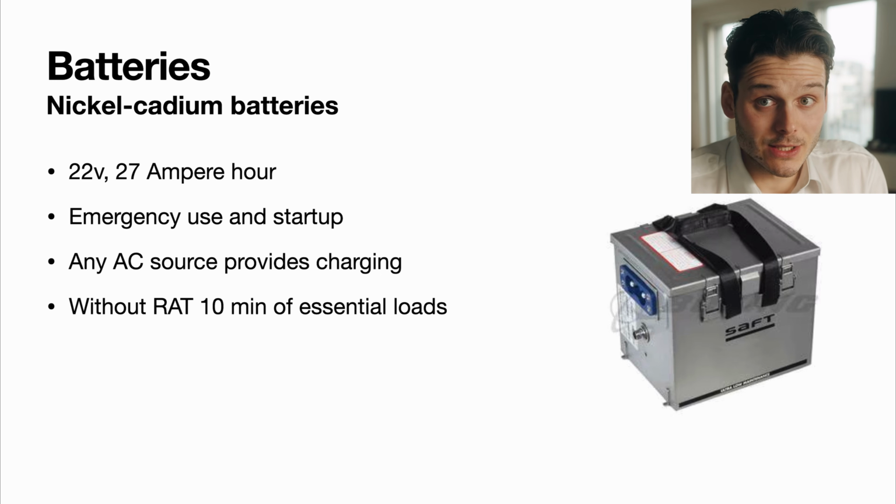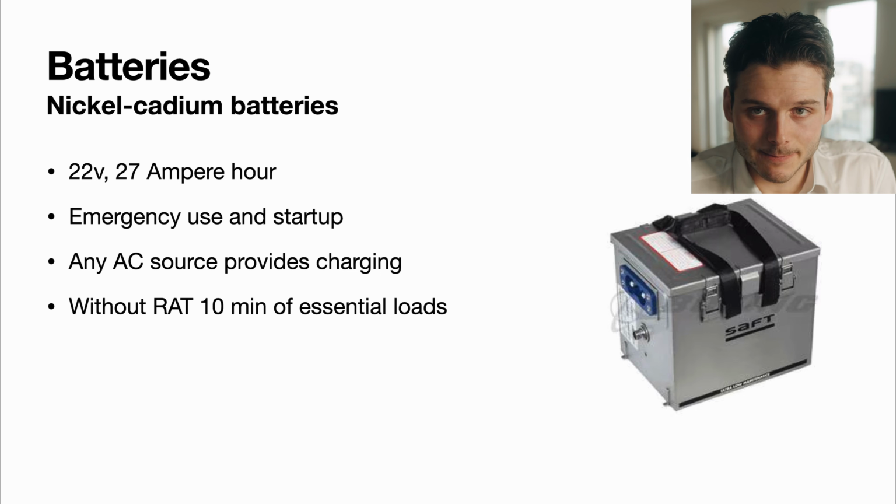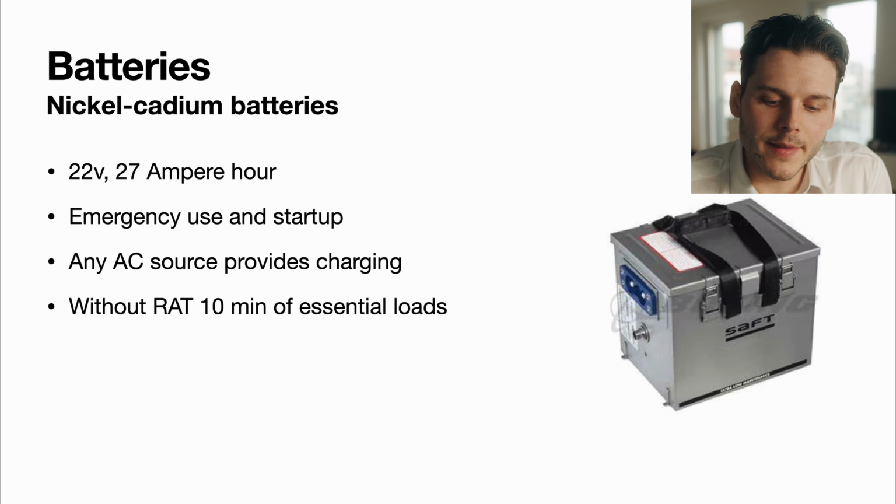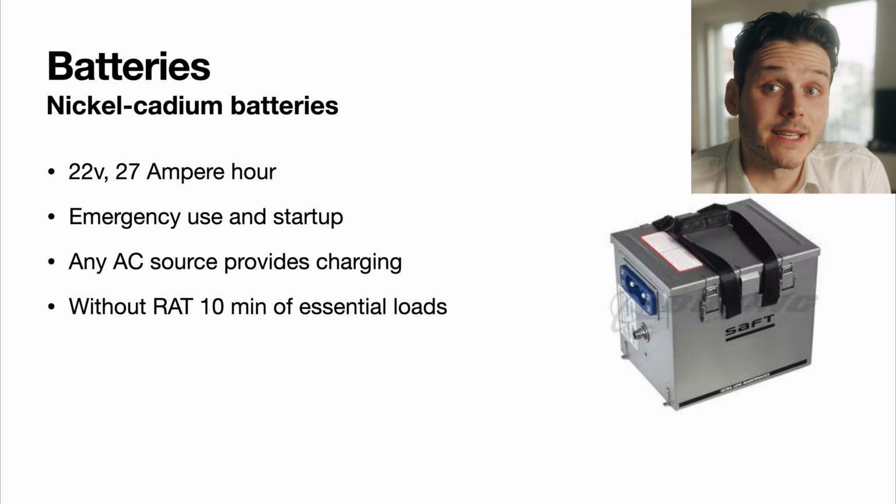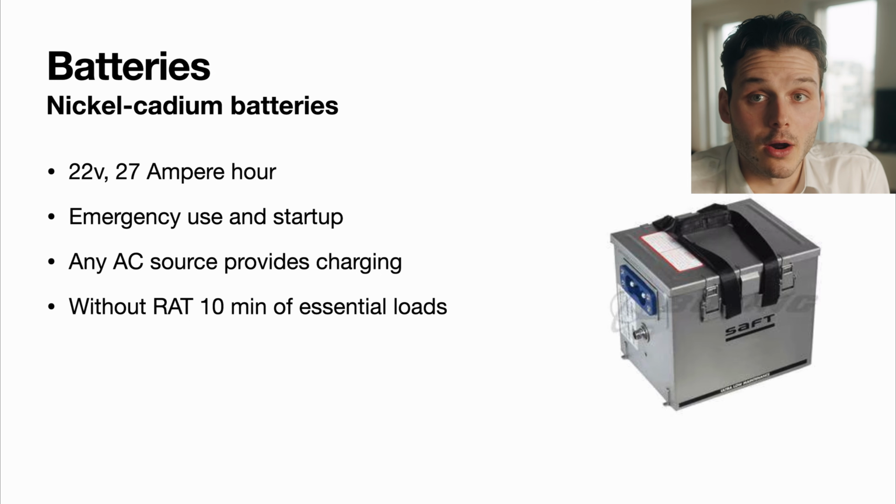Power on parking means we have the batteries and the emergency lights switched off. The reason for that is if we have power on parking with the battery switched on and the GPU fails, then the batteries will be discharging, obviously without any GPU, and also there will be a horn for the ground personnel if the batteries are on without the GPU for more than 5 minutes. So there will be kind of a horn or honk, whatever. I didn't hear that yet, but it happens.